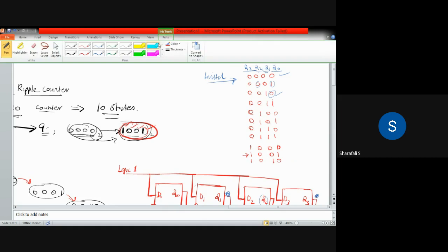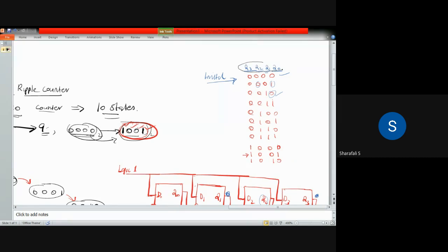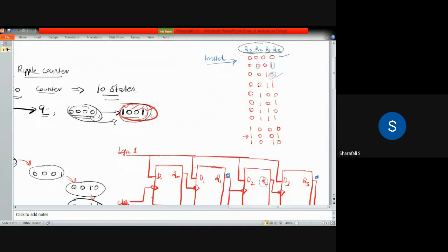And from here, I actually wrote the Q0 Q1 positions in the reverse way. That's why it was not working. So in this case, you can see this Q3 is 1 and this Q1 is also 1. Only in this particular state we can see 1, 1. If you take any other state, all of them have a Q3 value equal to 0 up to this state, so we do not have to consider any other values in this particular case, because it will give you 0 directly.